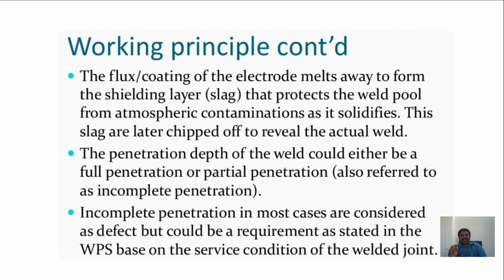The penetration depth of a weld could be either full penetration or partial. With incomplete penetration there will be cracks, porosity or holes, which come under defects in the welding zone. The defects associated with shielded metal arc welding are porosity, incomplete penetration, cracks, undercuts,